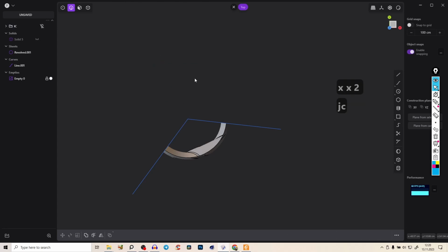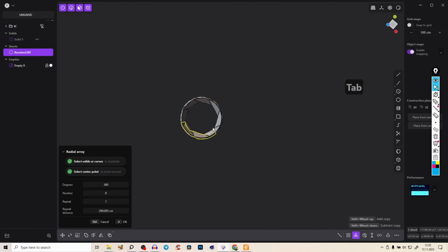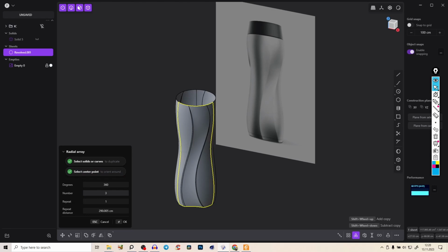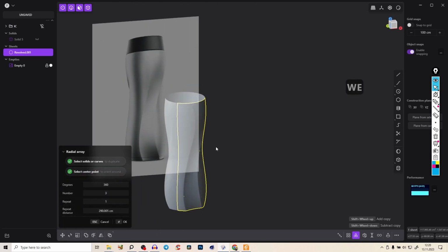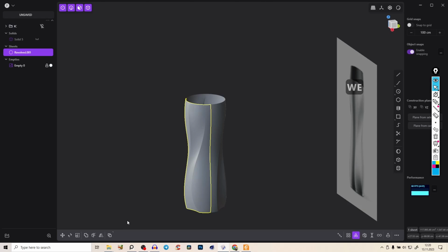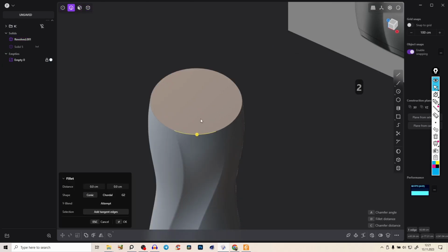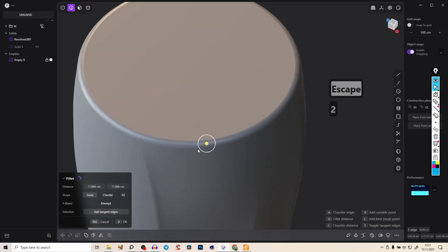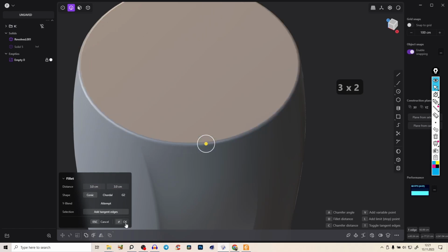This is selected, delete everything here. So we just have 1/3. Now select this whole piece and again radial array around the middle center and just use 3. And voila, you see that looks absolutely beautiful. Press OK. Join everything. Patch holes, so you close those holes, press 2, and give it here a very tiny fillet, just for the tutorial sake, here to keep things simple.